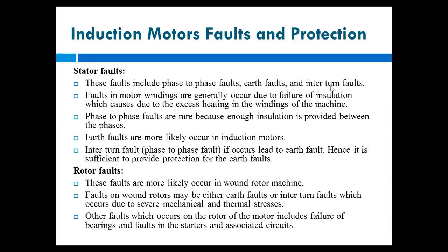Okay, so phase to phase faults rarely occur in these induction motors, and earth faults are more likely to occur in induction motors. Okay, means any one of the phases gets grounded. So that is nothing but the phase to earth fault. Okay, so such earth faults are occurring, means it is not only the phase fault.